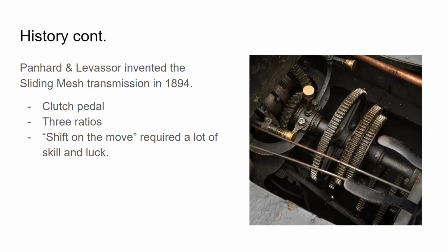And the way this worked, you have a small gear on this shaft down here that would mesh with this one up here. See this gap that's between this biggest gear and the middle gear here? These gaps were here for a reason. So this bottom shaft would slide over just a little bit, and this gear would mesh with this gear. And that could be your first gear.